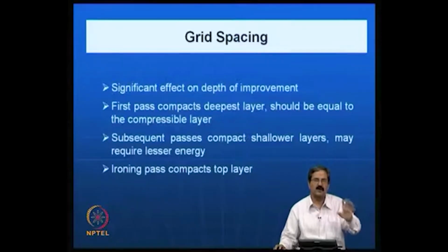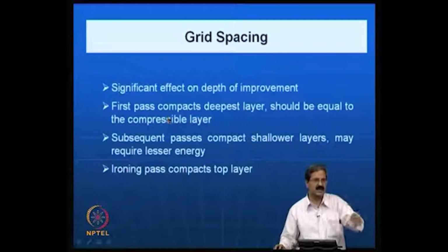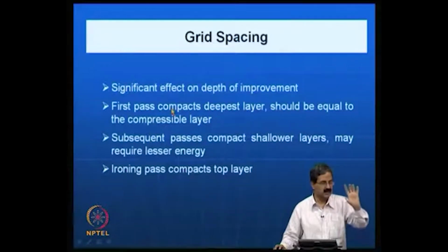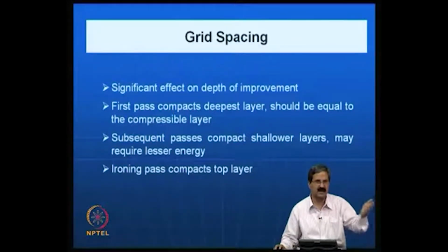So you must be able to compare how stress gets mobilized when you apply load. What happens is that shear strains get mobilized in the soil system. So you must do a numerical analysis, a finite element analysis, or some sort of detailed analysis, where you impose a load and calculate the strains, say strains of the order of 0.1% or 1%. Some sort of limitation one should have, similar to the depth of pressure bulb concept.